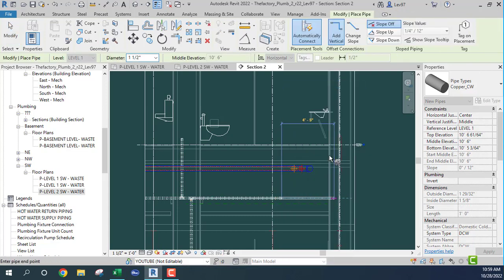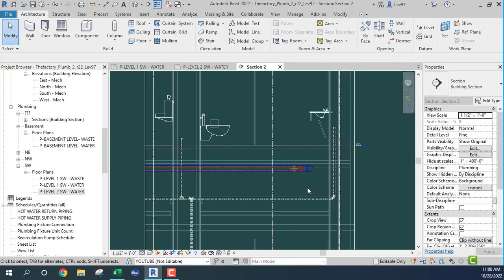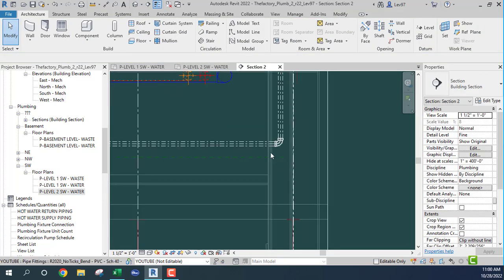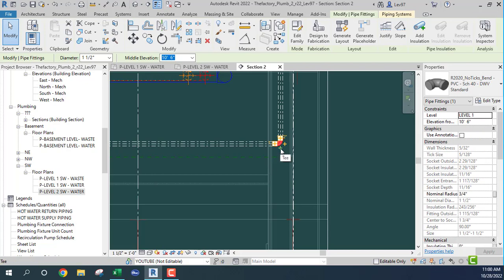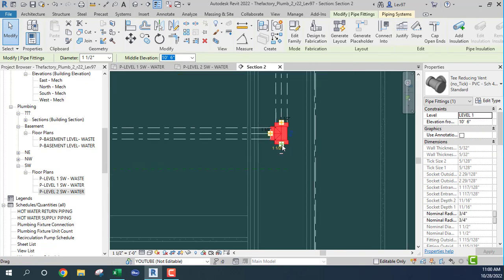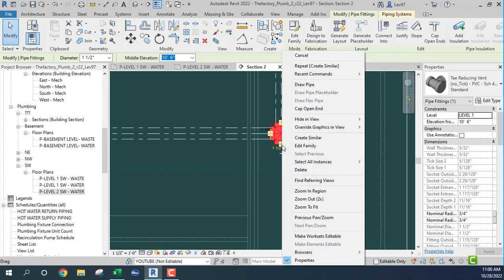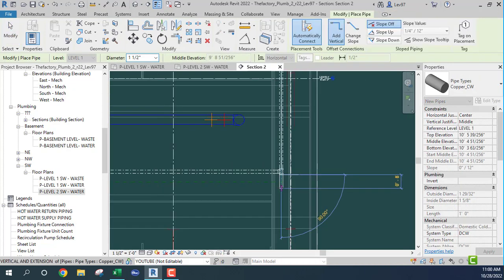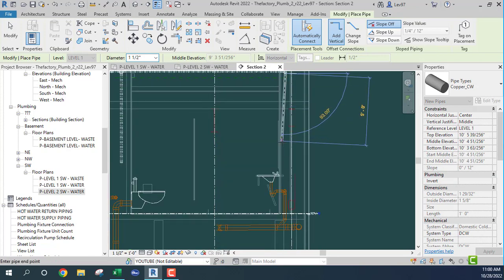and here. I'm gonna go up just a bit and select my elbow to create a T, which Revit allows me to do. And when the node turns green, I'm going to draw a pipe off that node and go down and select my fixtures on the first level.